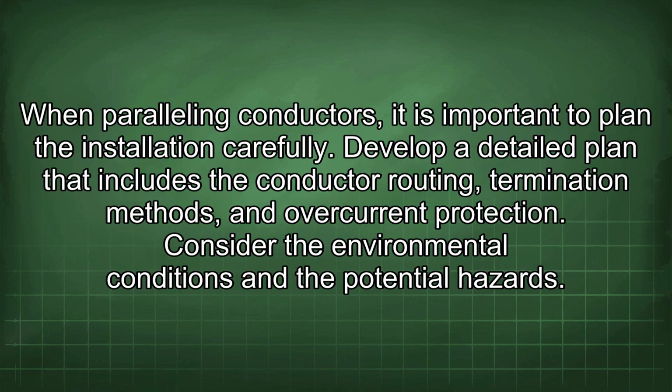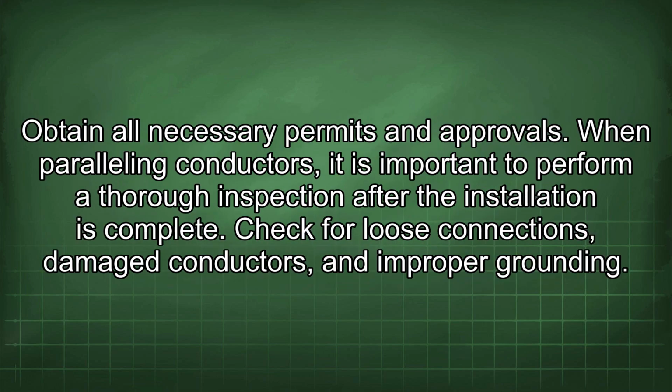When paralleling conductors, it is important to plan the installation carefully. Develop a detailed plan that includes the conductor routing, termination methods, and overcurrent protection. Consider the environmental conditions and the potential hazards. Obtain all necessary permits and approvals.